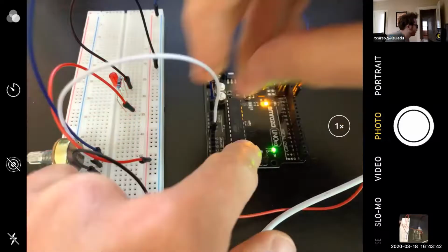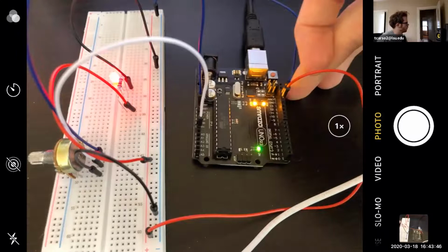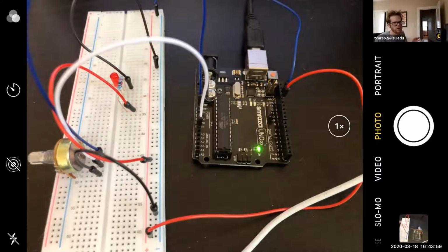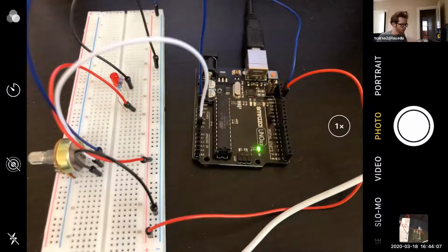So our analog input pins are right down there where I plugged it into, and we have 5 of them. And what these are going to do, they're analog to digital converters, and they're converting the analog signal of the potentiometer, which goes from 0 to 5 volts, into a digital signal from 0 to 1023. So it's mapping them with a linear function between those ranges.